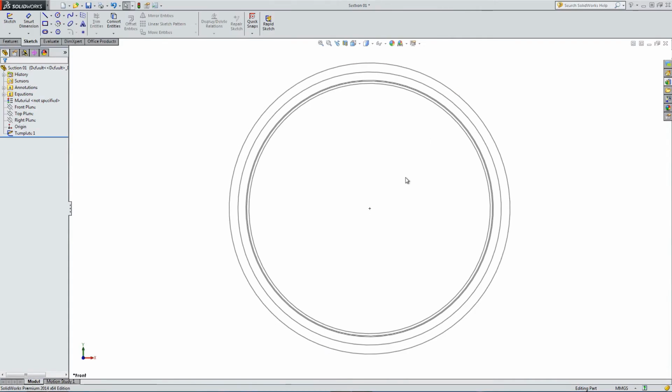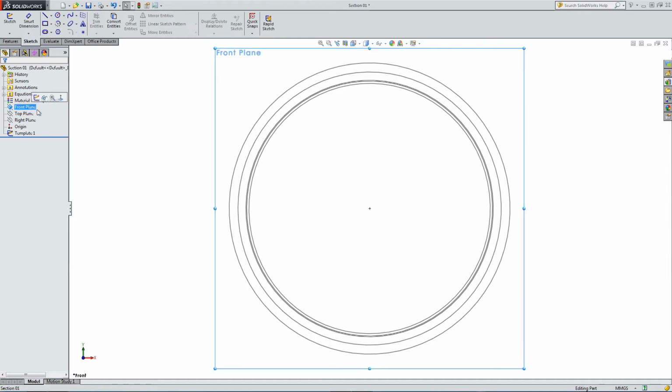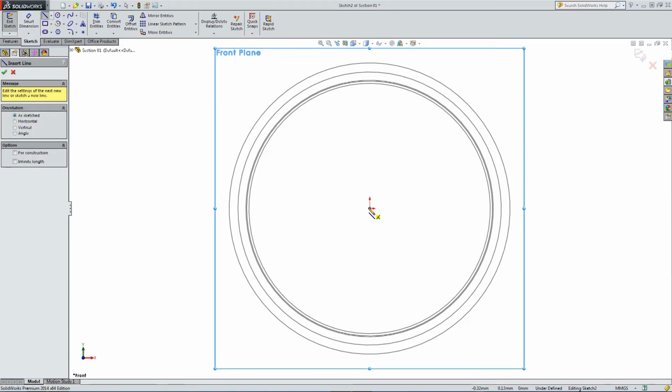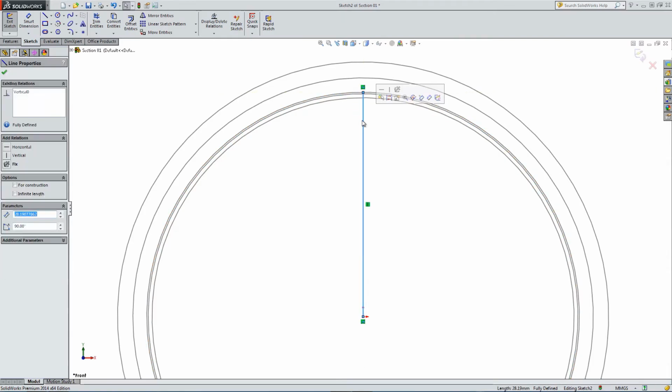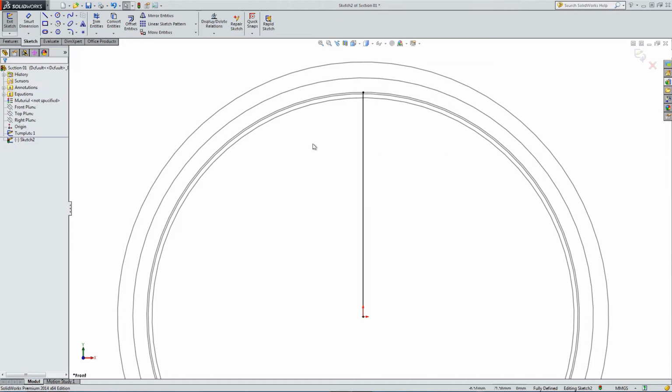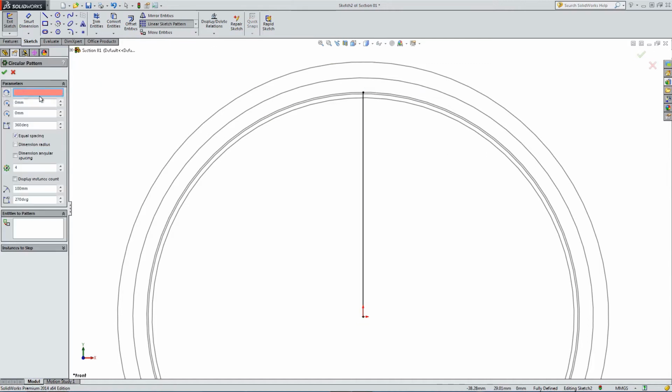Okay, let's now start forming the involute curve that we're going to use to form our gear tooth profile. So a new template sketch on the same plane. Give ourselves some reference geometry to start working with. I'm not going to form an entire involute. We don't need the whole thing.